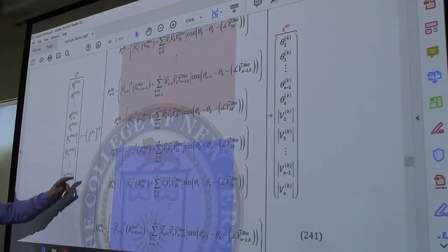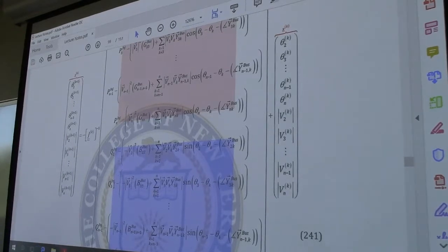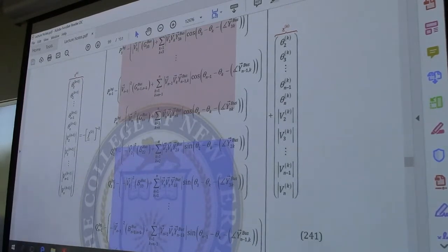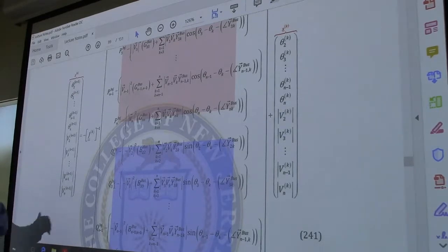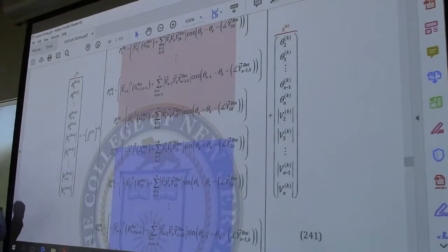And we still haven't given the specifics on this Jacobian. So you can split this up into really two different halves. I mean, you can't split it up in terms of the calculation. You need to calculate everything all at once, but there's definitely two halves to this. All the P's go along with the deltas. All of the Q's go along with the V's.